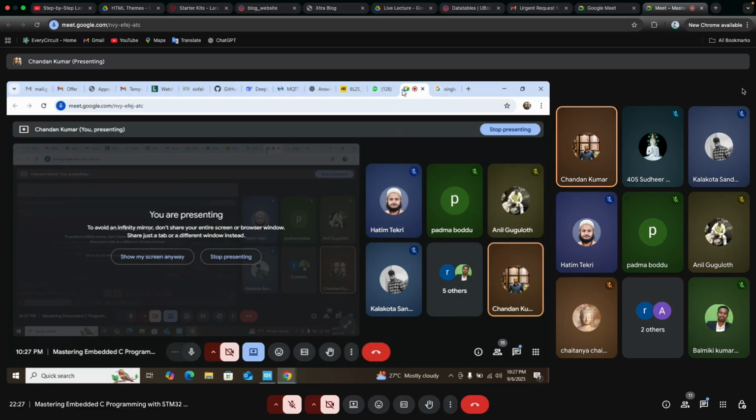The address by which it will select the slave is known as the slave address. So there is a term slave address, a unique address that identifies the target slave. It will be around 7 bits or 10 bits. Once I explain the theory, I will show it to you.